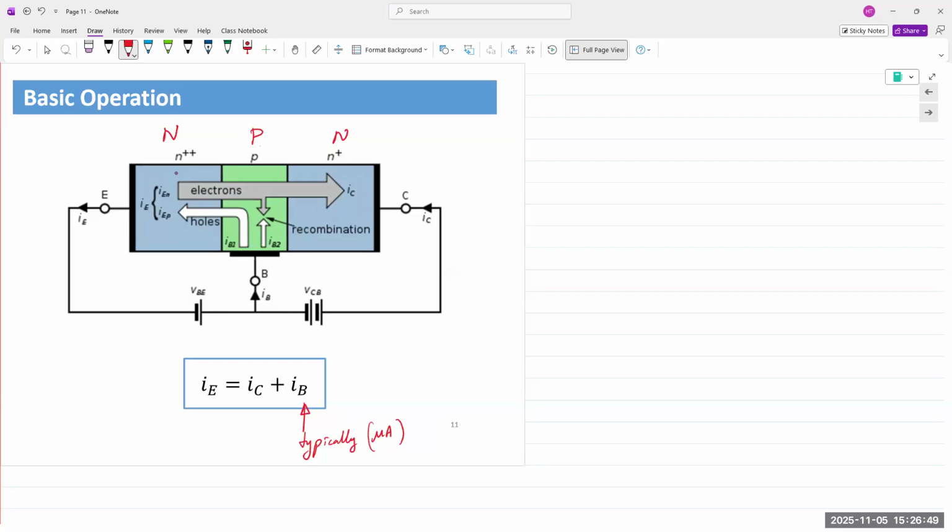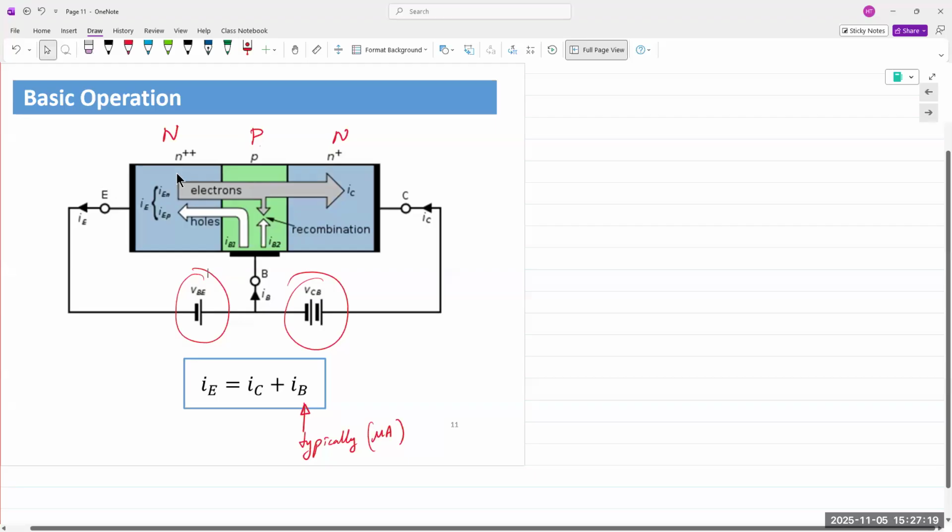So the question being asked is, why are we biasing in this way? And the answer is, well, in the question that we have, if we forward bias this, yes, there will be current flowing through, and we look at both modes of operation when both are forward biased. But essentially, if we do not want to use them just as two back-to-back diodes, and we reverse bias the second PN junction, then yes, we can control the flow of current that is actually flowing through there.